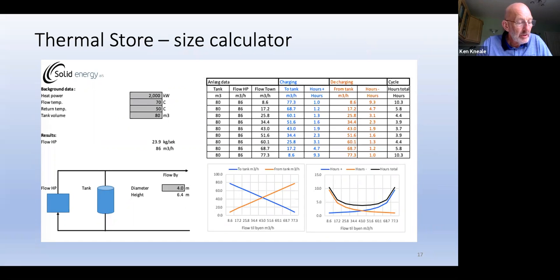Lastly, just to digress a little bit away from flow and return temperatures and COPs, once we have the lowest system design temperatures possible and a heat pump that delivers the highest possible COP, we also need to size the thermal storage. And we need to do that for two reasons. One reason is to extend the on-off cycle of the heat pump, keep it running for long periods of time so that we extend the expected life of the components of the heat pump.